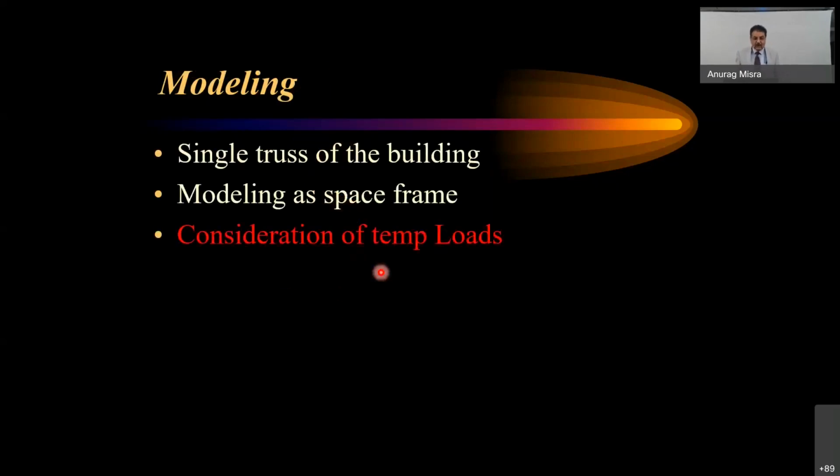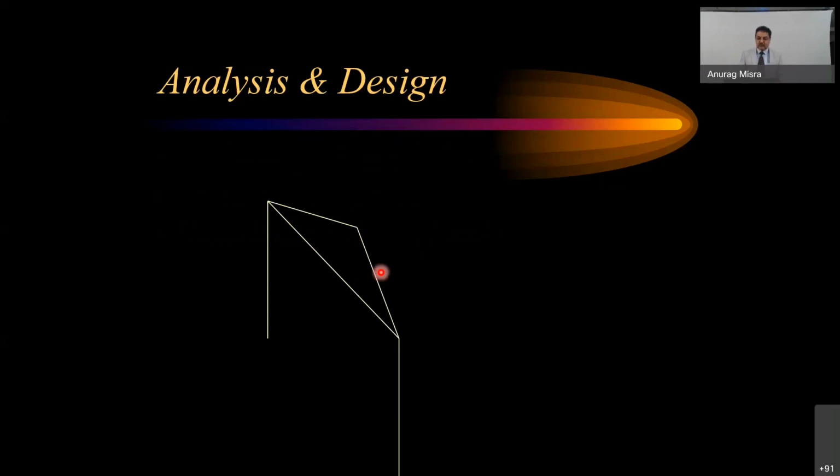Then also we have to consider the temperature loads. Wherever we are not considering temperature loads, the building has to be broken at certain intervals, and proper precautions have to be taken for the making of the joints, etc. So when we are designing it as a single portal, usually we don't bother much about the steel temperature loads.